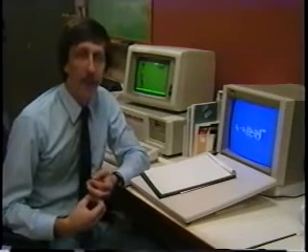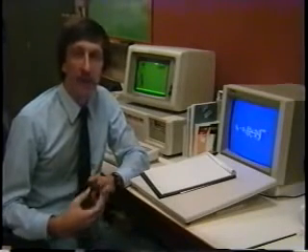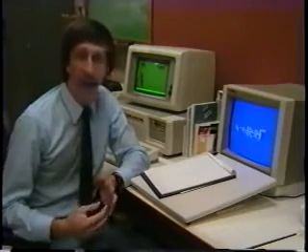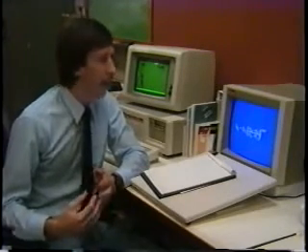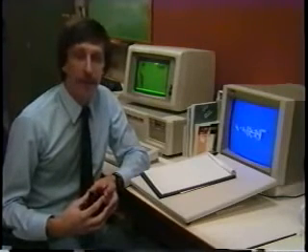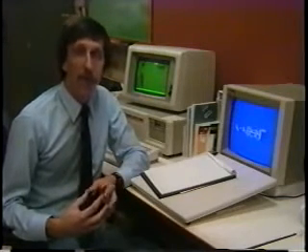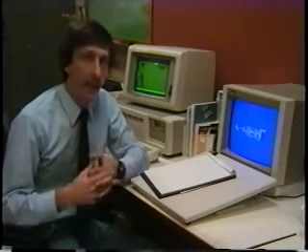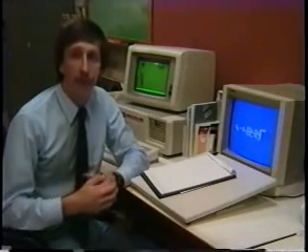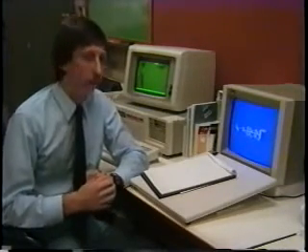And with that model, you can now play these what-if games. What if the fire happens when the pumps are off due to a power outage? What if the fire happens if the tanks are empty or very low for some day? You can't really do this out in the physical world because you'd be interrupting someone's services. But by getting the data from the field and then taking it back and combining them with the capabilities of a computer model, you can do so much more than you can with just the results of the test as we used to be able to do in the old days only.